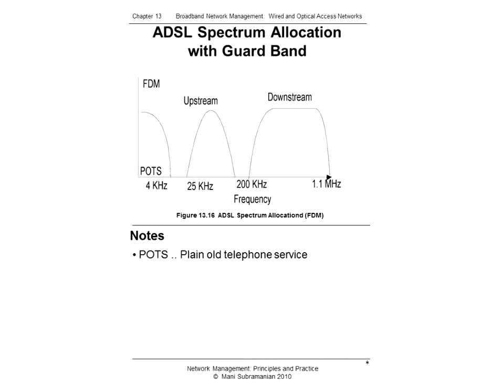So in echo cancellation, upstream and downstream bands, both of them overlap, but they are separated by a technique that we call as echo cancellation. So using echo cancellation, the low frequency end of the spectrum is made available for downstream, and therefore it increases the overall downstream spectrum band.